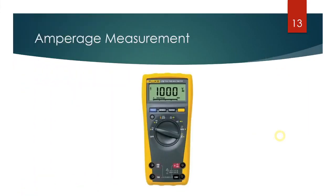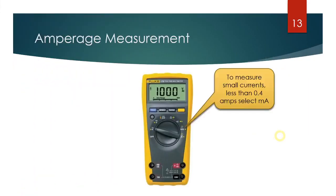Okay, let's look at how we're going to measure current. There are two settings for current. Now you would think one's for AC and one's for DC. No, actually we're going to measure current as either low amperage current or high amperage current. This first selection, all the way over here, is for currents that are less than 0.4 amps or 400 milliamps.